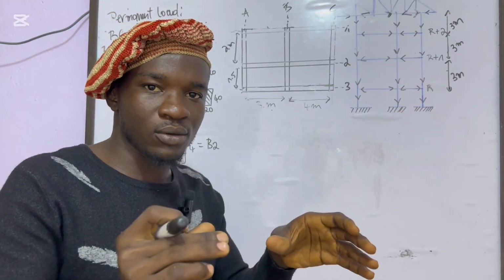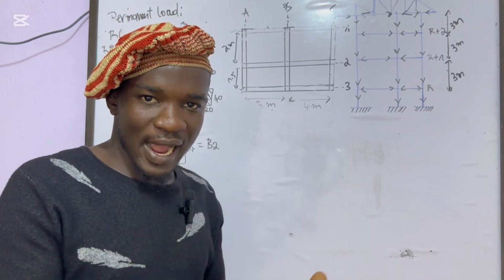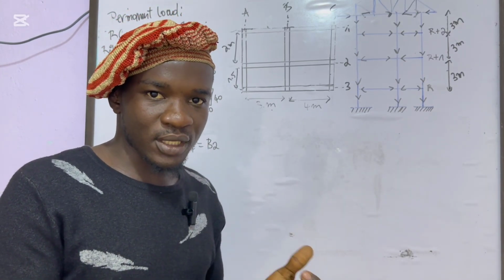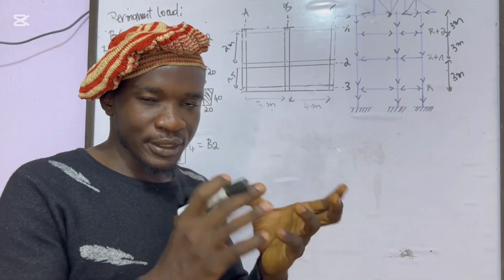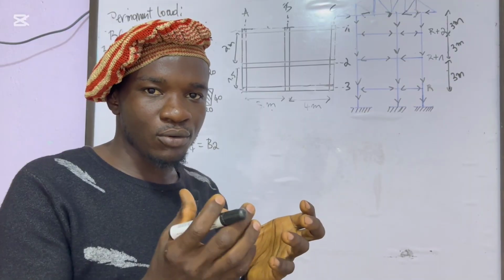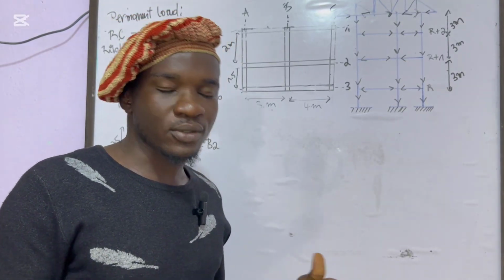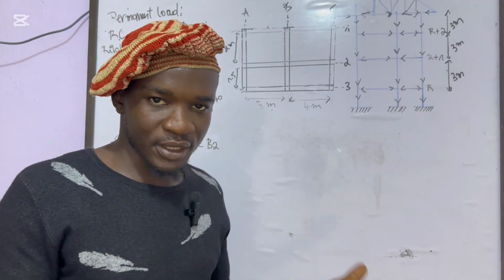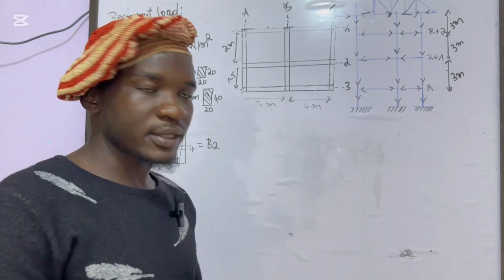to evaluate the load of the influence area that is being carried by the reinforced concrete column, in such a way that you can have the exact value of the load that will be used for the design of that reinforced concrete column, so that you'll be able to provide a section of the steel needed for the reinforcement. All right, so thank you very much.